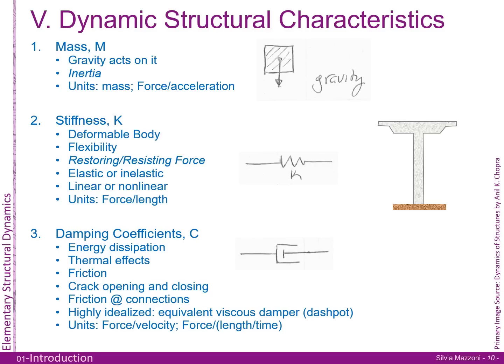We talk about stiffness. Sometimes you can look at it as flexibility. One is the inverse of the other. It's a restoring force or a resisting force. It's pretty much how much force you have to apply to a system so that it will deform. And also it's the force that the system will resist to try to bring it back to its undeformed configuration.